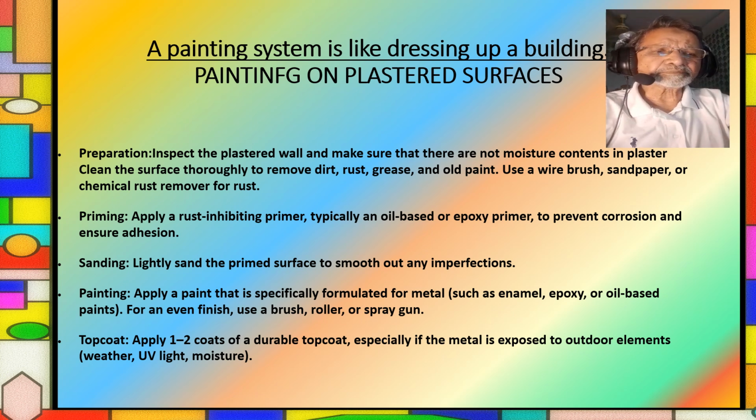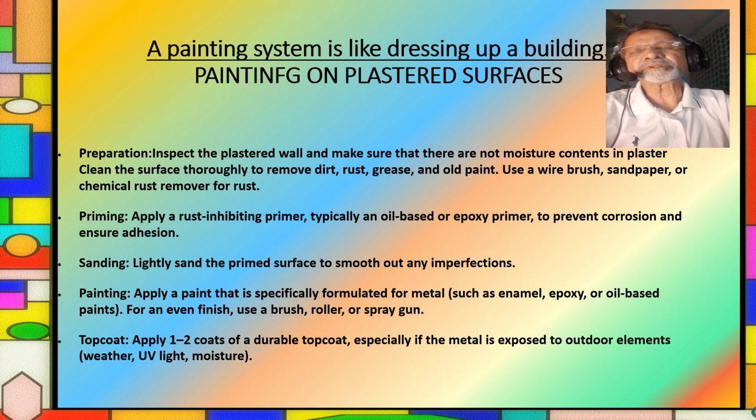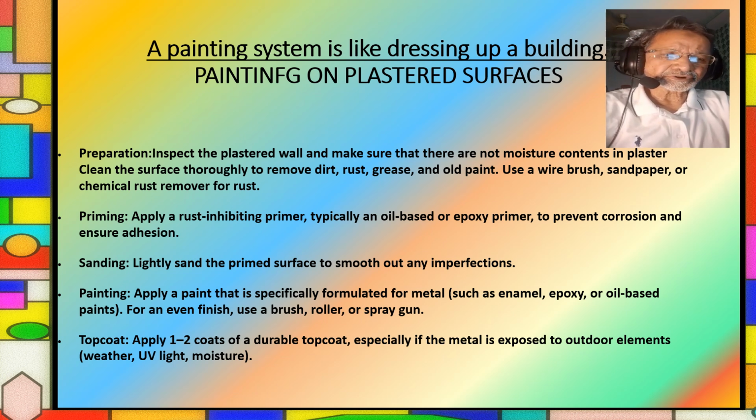To detect the moisture, there is an instrument to be used to find out how much moisture is contaminated in plaster. If painting is done on moist plaster, an adhesion problem may arise. So always try to completely dry the plaster surface so that there is no problem.